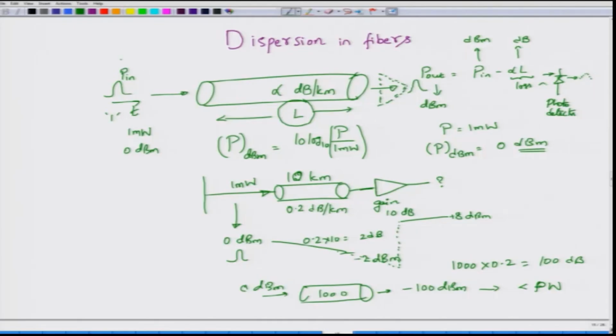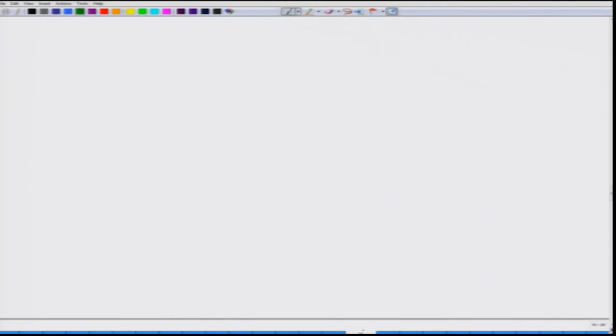So, the maximum distance of fiber before we need to place an optical amplifier, for the system operating conditions, is called a span. Okay. So, what this attenuation does to our optical pulses propagating in the fiber is to reduce the span length. Okay. So, that was attenuation. Just to summarize the first few minutes that we have talked about, attenuation limits the maximum span length.